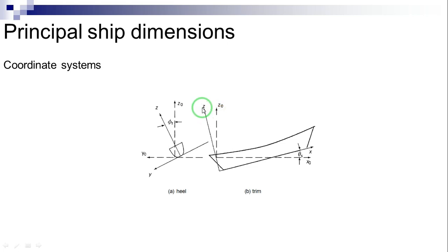A rotation of the ship fixed system around an axis parallel to the x-axis is called heel if it is temporary, and list if it is permanent, also referred to as loll. The heel can be produced by lateral wind, by the centrifugal force developed in turning, or by temporary transverse displacement of weights. The list can result from incorrect loading or from flooding. If the transverse inclination is the result of ship motions, it is time varying, and we call it roll.